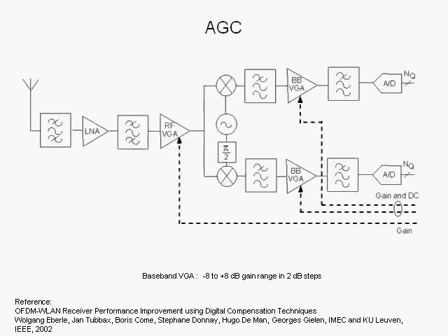In particular, we're going to talk about automatic gain control, since AGC is a key issue in the design of OFDM systems, where we have a very tight interaction between the baseband digital demodulator and the RF analog front end. AGC is very important, in particular to reduce the requirements on the dynamic range of the analog to digital converters, and also to actually achieve good performance over a wide dynamic range and reduce the requirements on some of the key components in the analog front end.